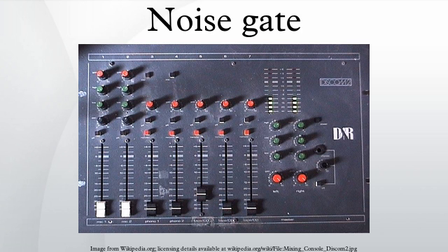Audio noise reduction: in audio post-processing, noise gating reduces steady noise sources such as rumble from LP records, hiss from audio tape, static from a radio or amplifier, and hum from a power system, without greatly affecting the source sound. An audio signal such as music or speech is broken up into many frequency bands by a collection of overlapping band-pass filters, and if the signal amplitude in any one band is lower than a preset threshold, then that band is eliminated from the final sound.